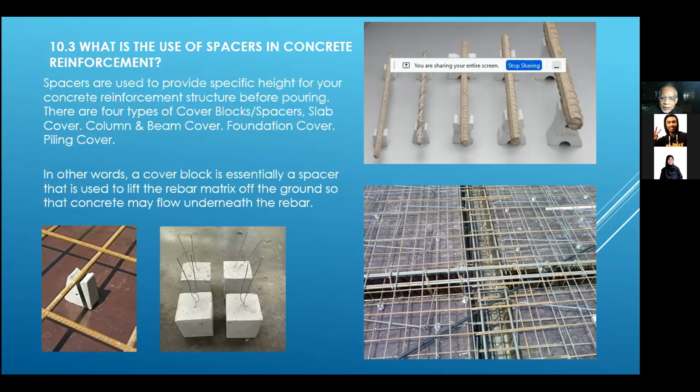At the site, we always have a form. Normally, once a contractor has completed all this placement of reinforcement, they will inform all parties for inspection before they pour concrete. They plan to pour concrete this afternoon, and then they ask us to go in the morning. Sometimes they give one day's notice, saying tomorrow the concrete mixer will come and pour. But when we check, if a lot of amendments are needed, you have to cancel the order. This is very important because once you pour the concrete, you can't see anymore. Everything is inside.